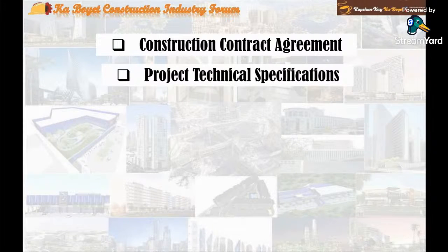execution part. The general information part defines what are the items included in the section. Related sections, section references, required submittals, quality assurance requirements, required warranty, etc. The product information gives the required specifications of materials, equipments, components, and accessories needed to do the work as per relevant design drawing plans and in compliance with the contract. And the last is the execution part. This defines the requirements for inspection, installation, termination, field quality control, etc.